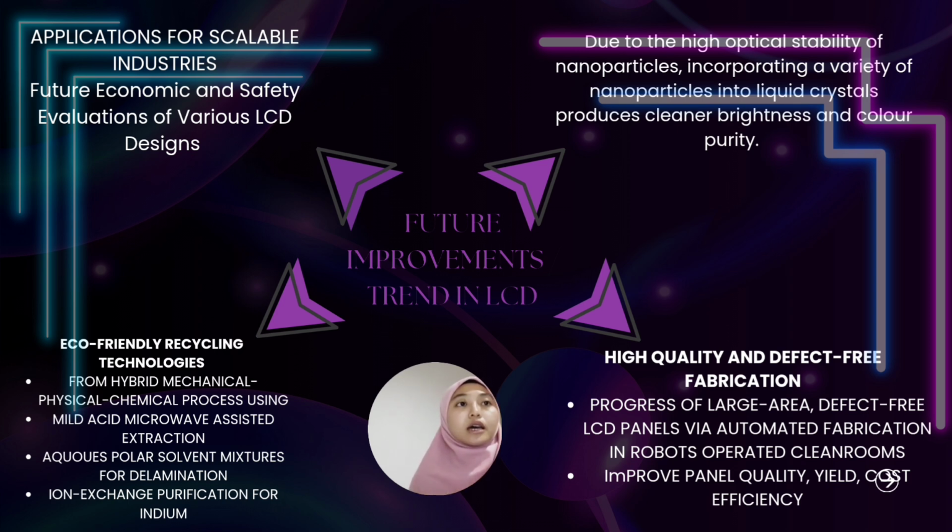The second one is the high optical stability of nanoparticles. When incorporated with the liquid crystals, it will produce cleaner brightness and color purity. The next one is the eco-friendly recycling technologies. It will form a hybrid mechanical, physical, and chemical process using mild acid extractions for less waste, aqueous polar solvent mixtures for delamination, and ion exchange purification for indium.